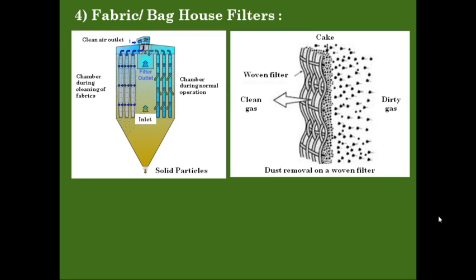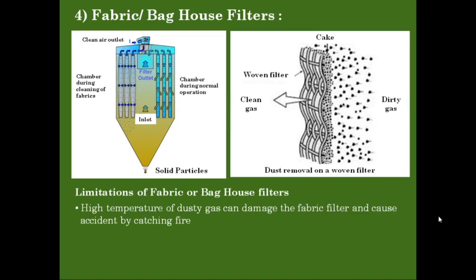We'll see what are those conditions under which we cannot use these fabric or baghouse filters. So limitations of fabric or baghouse filters are as follows. First, if the temperature of your flue gas or the polluted gas is high, then in that case it is not advised to use these fabric filters because the high temperature of the gas can lead to the damage of fabric filters and can cause an accident by catching fire.